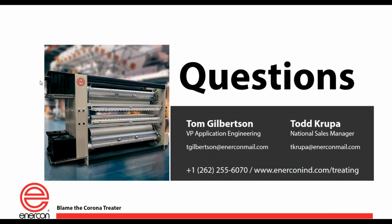I've got a question. To improve the lamination, someone uses primer combined with Corona treatment. Is that common? Oh yeah, it is common. On extrusion coating machines, for example, it's very common. You unwind, you go through a primer station, you go through a Corona treater, and you go into the extruder. It's very, very common.